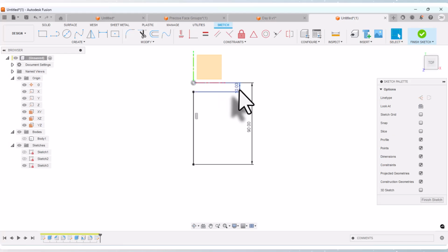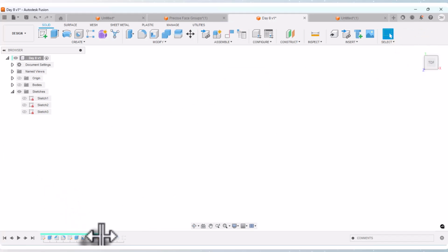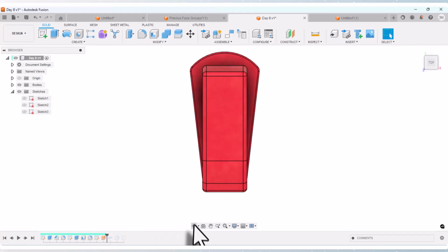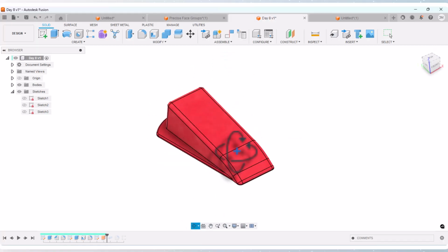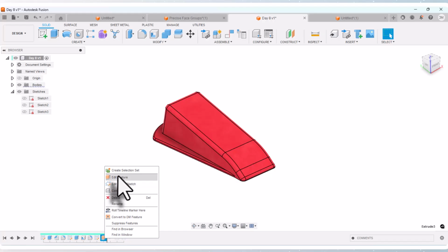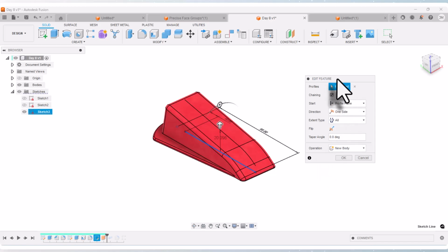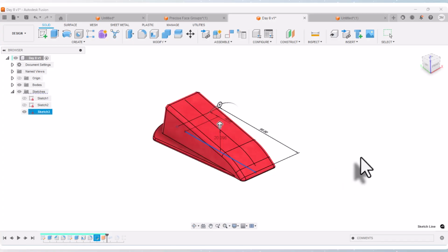Okay. And so I have created that line as was done in the prototype, and we'll finish that sketch, and on the timeline we'll go to the next step, and I'm going to rotate this around, and I see that this separate symbol here, if I right click on that and I edit that feature, notice that symbol, the color of it. I'm going to edit feature, and it doesn't really tell us here, but that color indicates that it's a surface body and it is extruded through all.